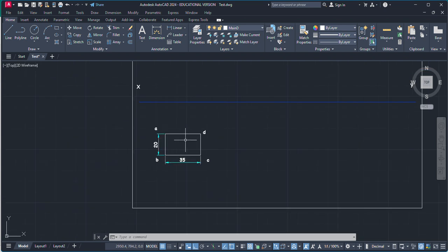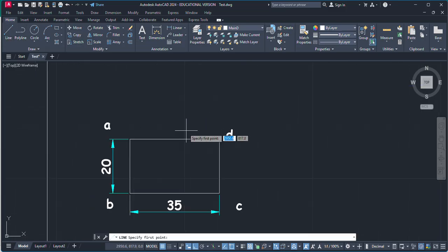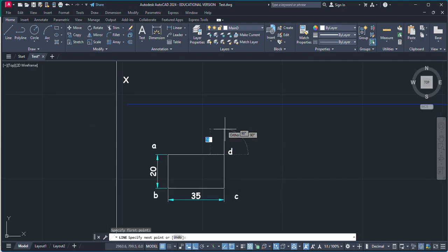This is the top view, and from that, if it is resting on HP on one of its edge AB, so the front view will be from this point to this point. I'm just going to change these lines to the construction drawing now. In the front view we'll have a straight line because this is a plane or lamina.